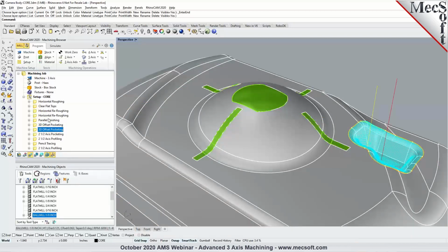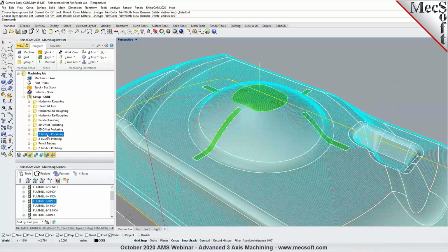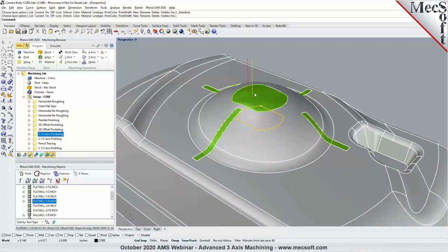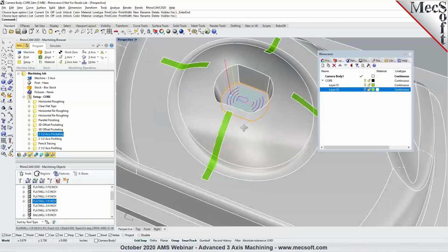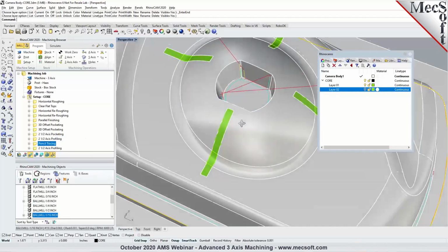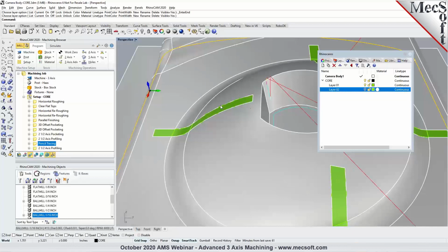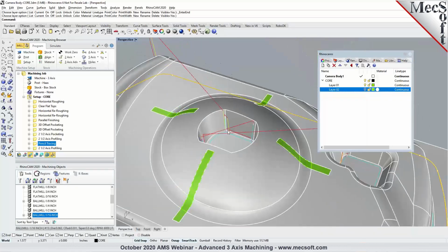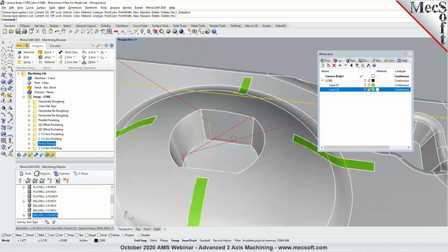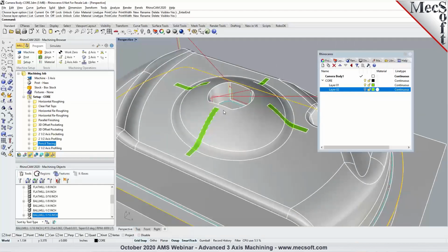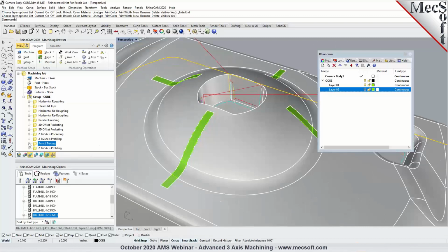So you can use them for programming your roughing and finishing toolpath. And finally, you can expose those areas by hiding those surfaces to generate your finishing toolpaths, or you can even do a combination of both 2 and 3 axis toolpaths to finish off those pockets. Or if you'd like to do a pencil tracing operation to go back and clean up, you can see this pocket has a draft on it, so the pencil tracing will be able to identify those bitangencies to clean up and result in a nice finish. Again, in this particular case, we are using a radius cutter, like a 16th inch ball mill cutter, to clean it up.